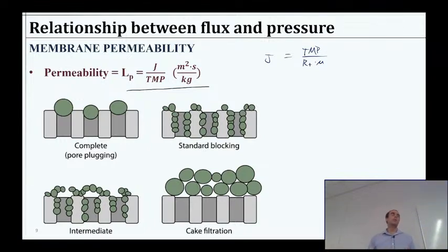And we can also look a little further on some of these models showing how the membranes could be fouled in particular. So we already talked about cake filtration, where particles now have to filter through the pores of those other particles or water has to filter through them. And these new pores might be smaller than the pores that were the membrane itself.